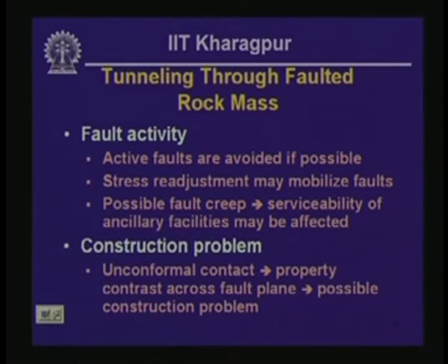Construction problems might also arise in case of construction of tunnels through faulted areas. The problem essentially involves the fact that faults are unconformal contacts in which the rock mass on either side of the fault plane could be of remarkably different stiffness and strength characteristics.